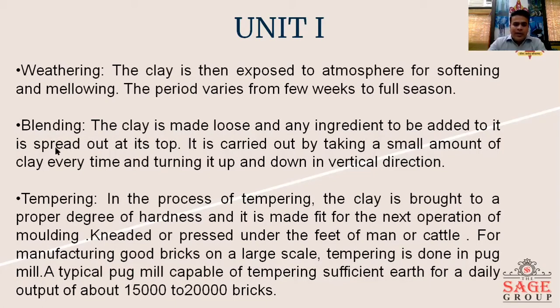Then blending is the process in which the loose clay and any ingredient material present in it is spread out at the top. It is carried out by taking a small amount of clay at a time and turning it up and down in the vertical direction. That means the thorough mixing of the prepared clay so that it forms a paste-like material, and any material present in it, pebbles or stones, can be extracted out.